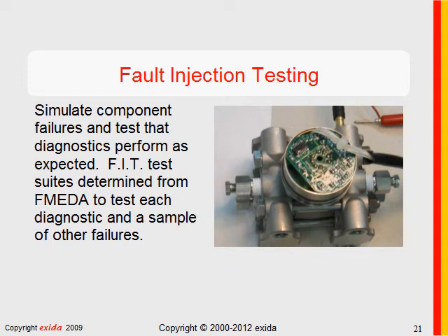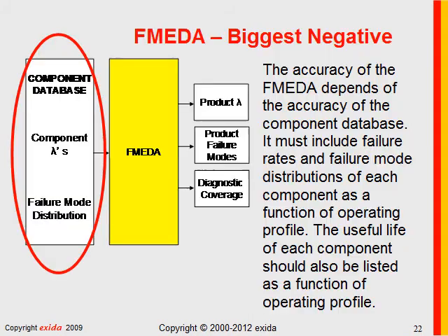Sometimes, in fact, it's essential that the various assumptions during the FMEDA are verified by testing, and most FMEDAs are backed up with a very detailed fault injection test on a particular product. So FMEDA is not just a theoretical calculation, it's a calculation backed up by testing. Now, what's the problem with FMEDA? The accuracy of the result depends on the accuracy of the component database. When you look at this picture, I hope that becomes self-evident.